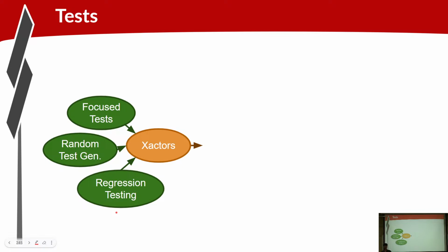And this is our way of making sure we don't go backwards. So as much as possible, as you're developing tests, you try to enable those tests as regression tests, meaning every time you make a change to the model, the regression tests will be run against that change and make sure they're still passing. So it's our way of making sure that we don't step backward. Anything that's in the regression test is a gating function for changes getting into the model, so they prevent bugs from getting into the design.